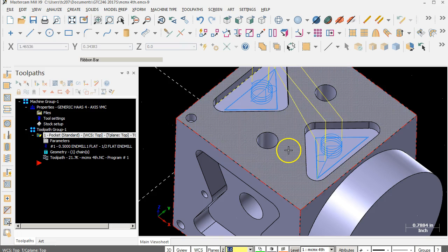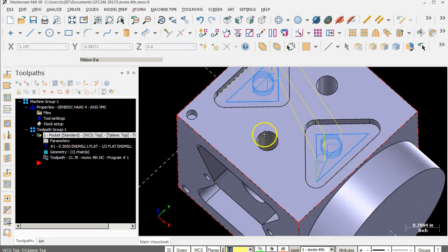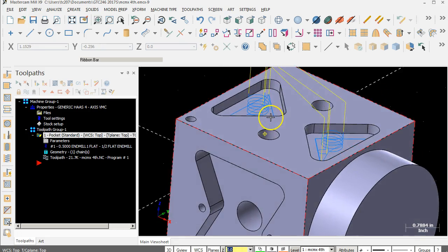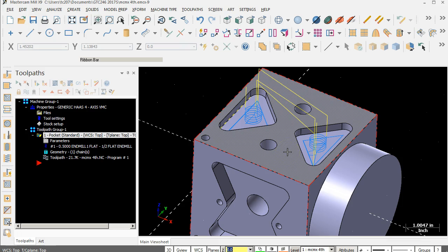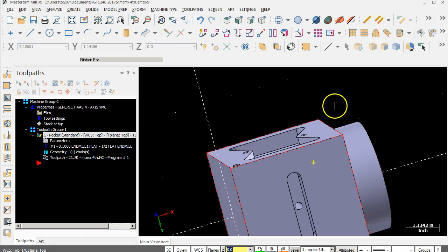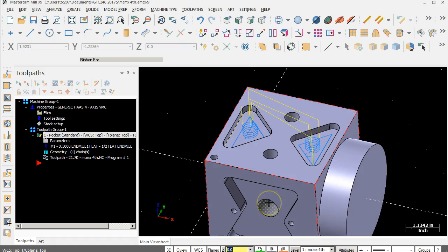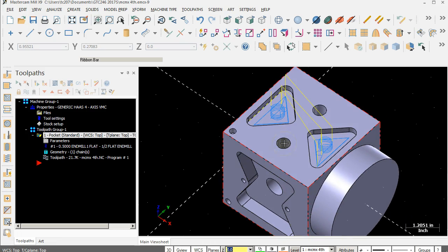So, goes in, does the finish pass, that all looks okay. All right, so the other thing of interest then would be, how do I want these holes to intersect? Because anytime that you're drilling through intersections, you're going to have additional chatter. You're definitely going to have burrs pushing into the other chambers or to the other axis. All right, so we're only going about halfway through. So, well, we'll think through. I can always reorganize these later if I need to do another face first.